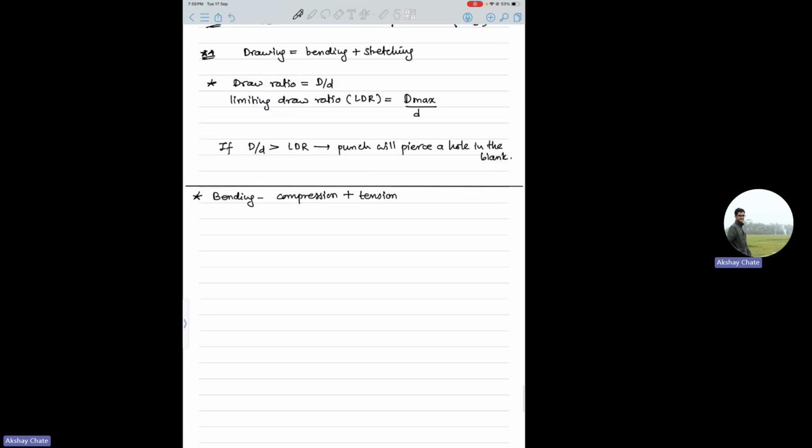And there is a very important question sometimes asked directly in the exams, something called bend allowance. So this will be your neutral axis while bending. Let's consider this is the domain of the bending. If you have theta, which is the angle of bend, and this is your r, which is the bend radius, in that case, the bending allowance is calculated as theta into (r plus kt), where k is called the stretch factor.